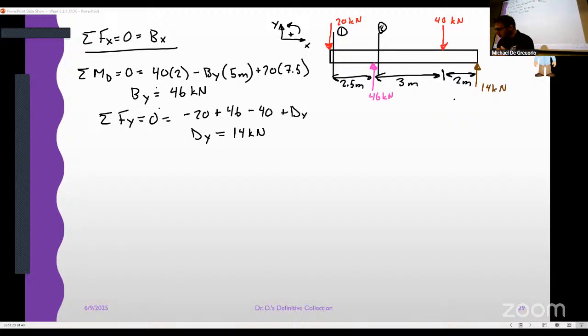Now, the last one, you have a choice. We're going to cut in the same spot, right after. So really that's on the 2. I know it doesn't look like it, but remember, it is a very small distance away from the force. We'll talk about it when we get there. So we've got 3 cuts. We're going to determine the shear, and this is enough for us to get shear and bending throughout the entire beam. Let's start with cut number 1.